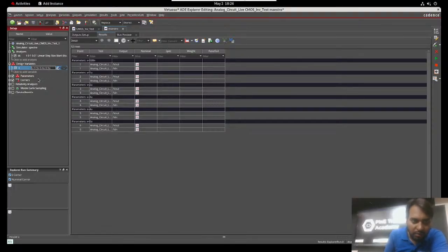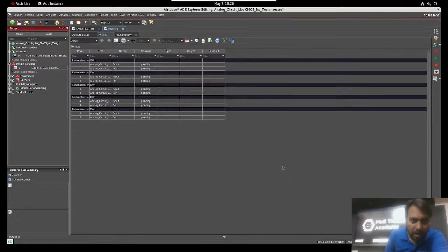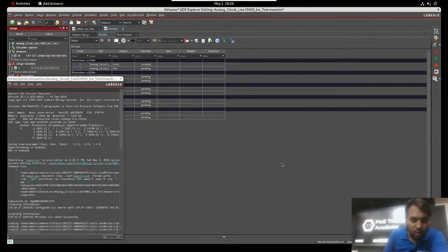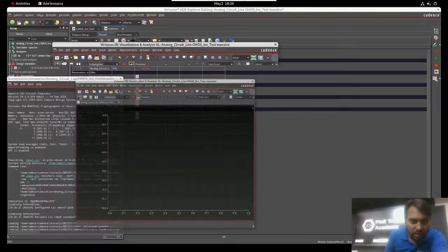So that we have a different x now. Now it will be 0.1, that is the finger width, and the PMOS will be two times that: 0.2, 0.4, 0.6, 0.8, and 1 micro. Let's try this. I am running it on the different widths, and now the PMOS width is lower compared to the previous one. Okay, there is a simulation error. Why would there be a simulation error?